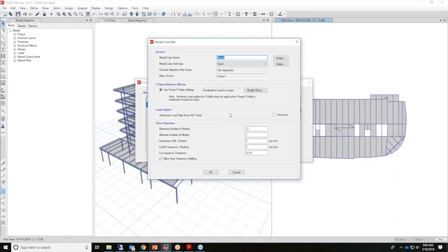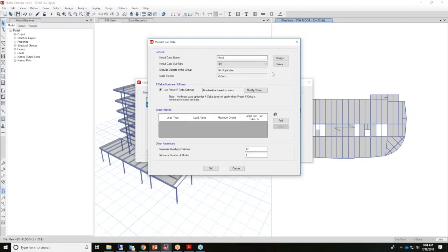Only pertinent mode shapes which occur in the horizontal plane are identified. Eigenvectors, on the other hand, use the full stiffness and mass matrices, which also account for vertical modes. So the eigen formulation is useful when considering, say, floor vibration, or out of plane vibration of, say, shear wall systems. The eigen application is also useful for locating model errors. So we can use either eigen or Ritz. We'll use Ritz in this example.